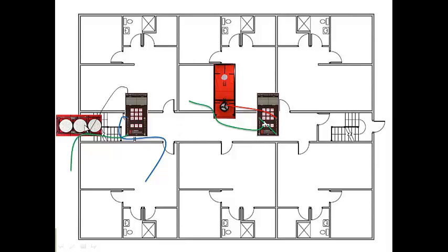And again, this hallway can be very turbulent. It might not be if we're a ways away from these fans. This area is probably going to be less turbulent, and we might not need to cap that or leave that tap. If it is really turbulent, we're not going to want to have that tap open, and we're going to want to run it to the adjacent hallway. But in this case, we might be far enough away from that fan, so the air really isn't too turbulent in that space. But just as a precaution, it's a good idea to be measuring in the same pressure zone that we're measuring our outdoor reference with.